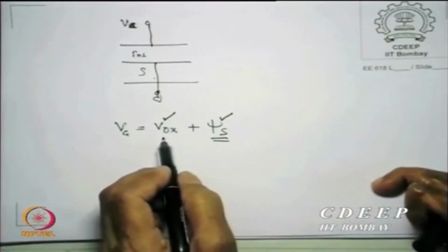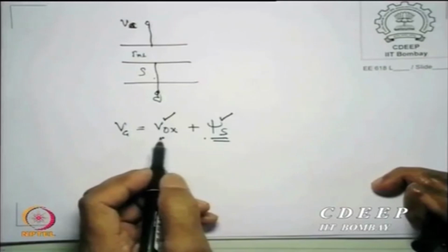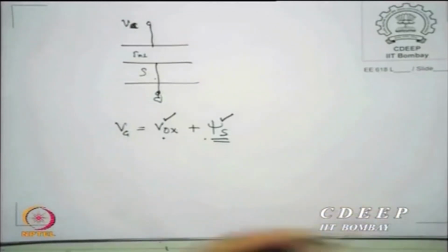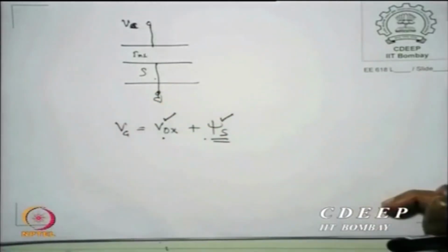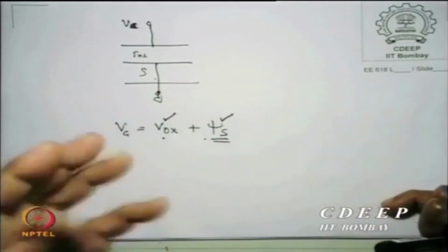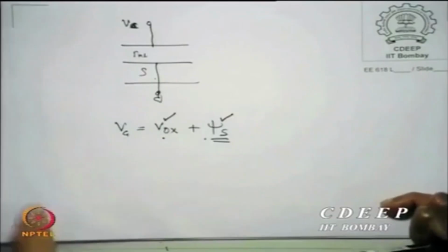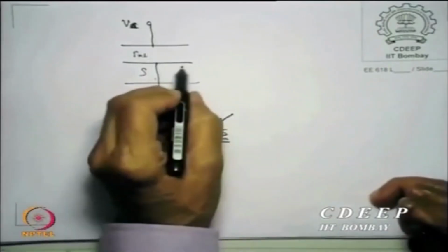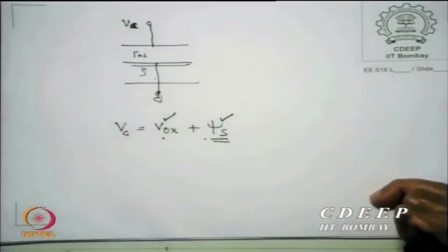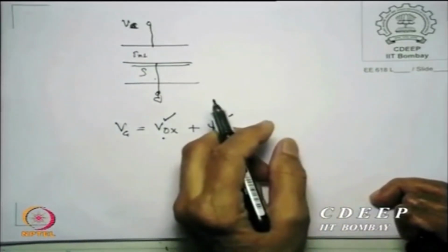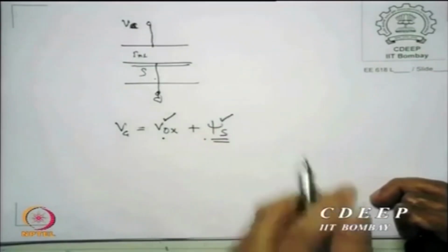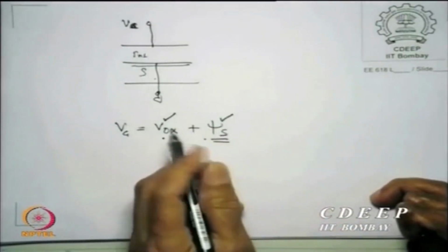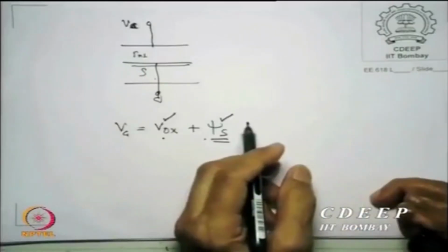Either one of them will increase, or both may increase, which are the cases of relevance. This potential drop across the semiconductor region we call the surface potential. Why is it called surface? Because charge is only near the interface, so potential will change only where charge is, by the law through which potential appears because of charge. Which very famous law relates voltage to charge?